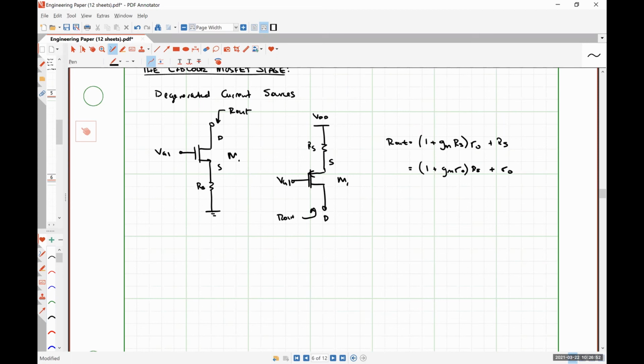And so we have a voltage drop over RS, which is effectively raising the level of our gate-source voltage to be operating in saturation, which is then confining the amount of voltage that we can see at the output with respect to our power supply voltage, VDD. So we still have that headroom limitation. We can negate some of that trade-off by, again, cascoding or degenerating with a transistor.